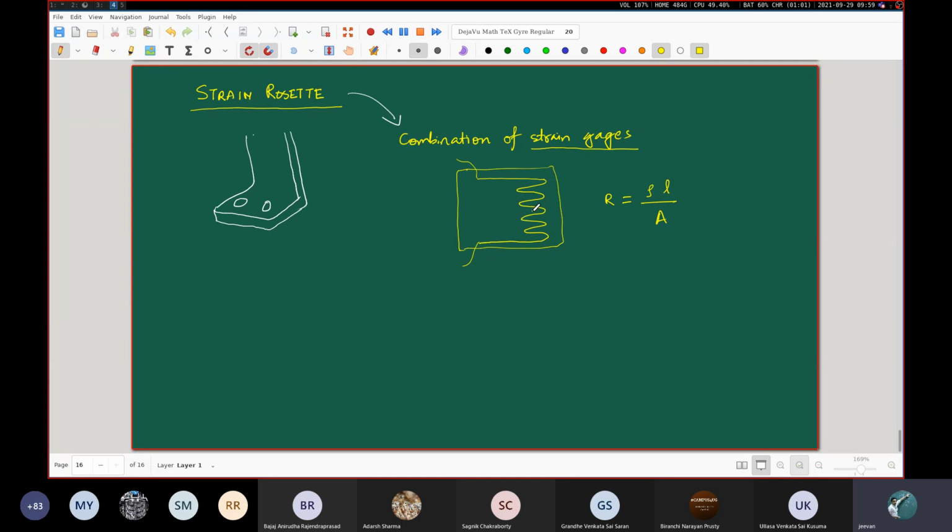But this is along a particular direction only. So this is equivalent to making those two marks that I had told you earlier. Instead of an optical device, you are using an electrical device to measure the normal strain along a particular direction. But despite the apparent sophistication of this technology, you are still limited to determining the strain only along a particular direction.